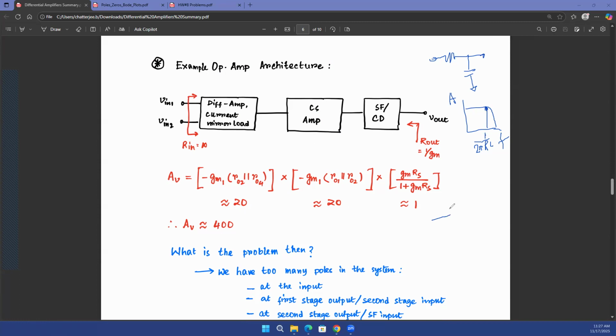On the other hand, if I had a capacitance in the series path and then a resistance in the parallel path to ground, that works as a high-pass filter. Again, something that you have seen in your homework number 3, that if this is F, and again, this is amplitude, then my pole frequency is again 1 over 2 pi times RC, whatever value of that resistance and capacitance is. Now, why am I saying that we have too many poles now?